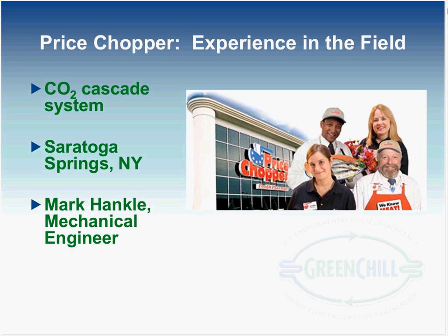Yeah, I think so. I think in terms of normally you all aim for a short payback, and in this case it could be between 5 and 15 years based on utility rates being high or low in certain markets. Let me ask you though, is that now universally true for Cascade and secondary loop systems using CO2 as a secondary fluid, or is there a difference between those two, for price range, in terms of payback period?